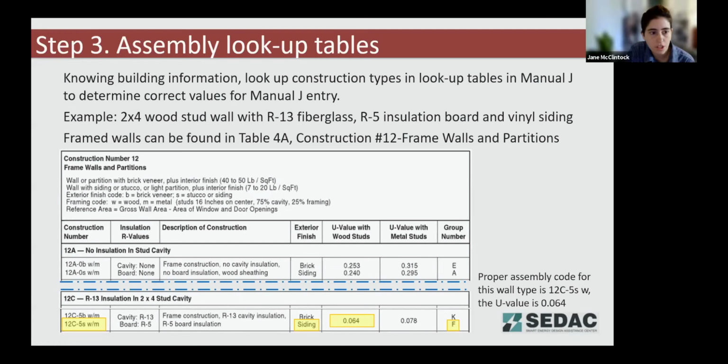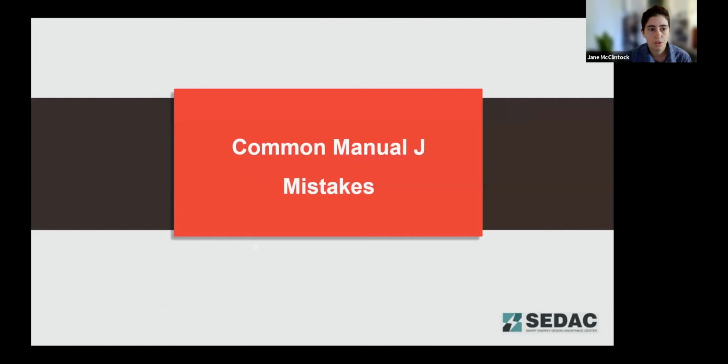We've got one more question in the chat from Greg. Can this be used for just cooling, such as when adding mini split units to an existing boiler? And you could, but if you're designing those mini splits just for cooling, you'll still go through the same process. But you need not design them to provide the full heating load if they're just going to be used for cooling and redundant for heating.